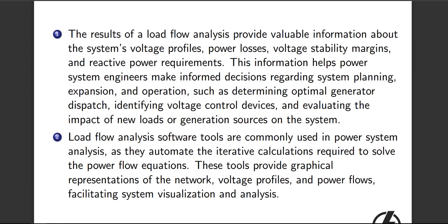The results of a load flow analysis provide valuable information about the system's voltage profiles, power losses, voltage stability margins, and reactive power requirements. This information helps power system engineers make informed decisions regarding system planning, expansion, and operation, such as determining optimal generator dispatch, identifying voltage control devices, and evaluating the impact of new loads or generation sources on the system.